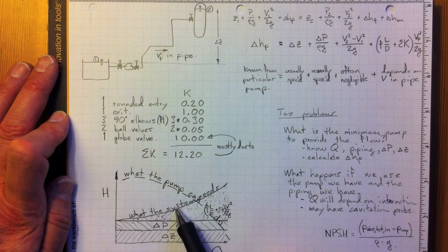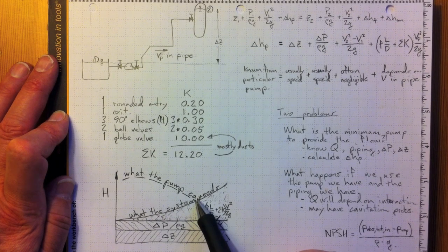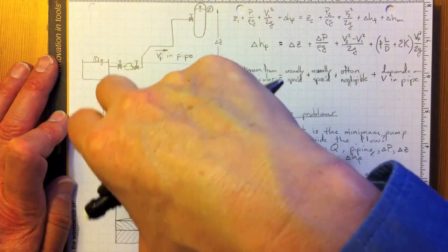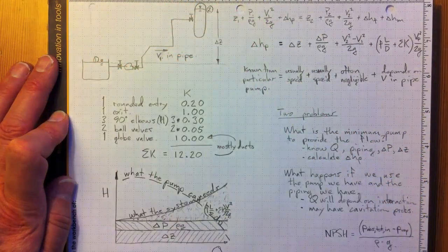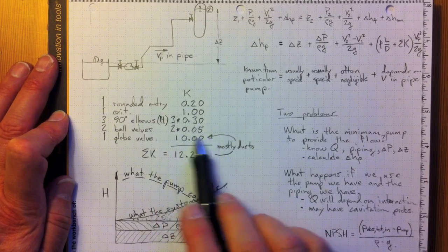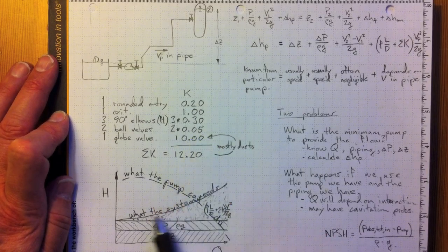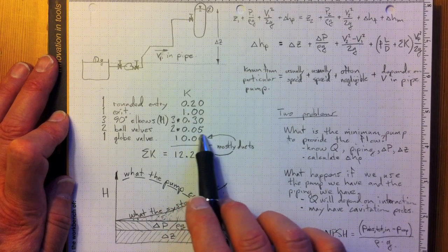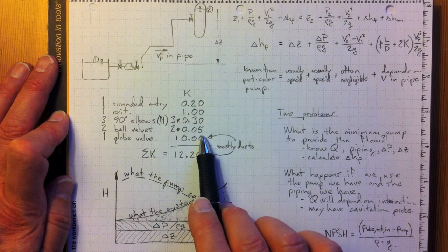If we had that extra capacity, then instead of operating down here, we'll wind up operating here at a considerably higher flow rate. We may or may not want that. We may start turning one of these valves closed to slow down the flow by increasing the loss coefficient and throwing away that pump energy with extra losses that we don't need to have.